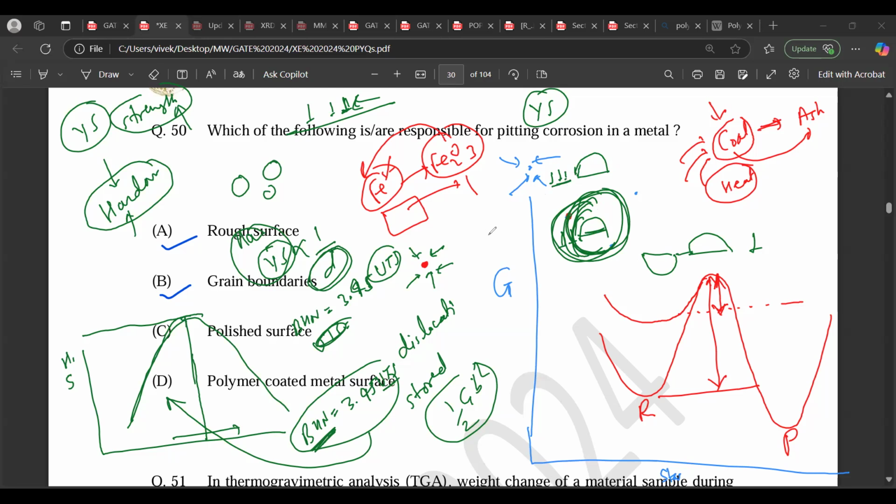The same idea applies to grain size hardening, or grain refinement. The smaller the grain size, the bigger the strength. Why? Because if the dislocation moves, it will start piling up at the grain boundary. Every grain boundary is a collection of screw dislocations and edge dislocations, whether it is a twist boundary or a tilt boundary. So there are a lot of dislocations along the grain boundary, and it has to change the slip plane.